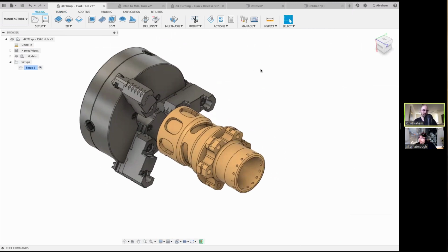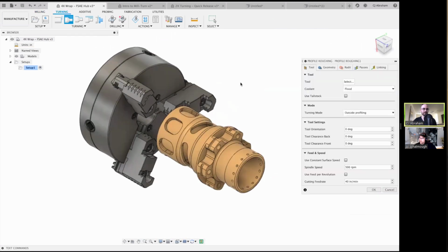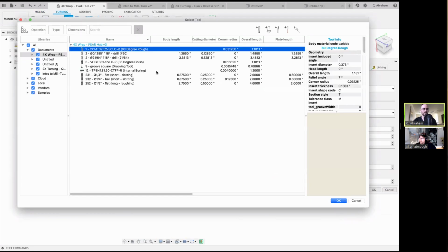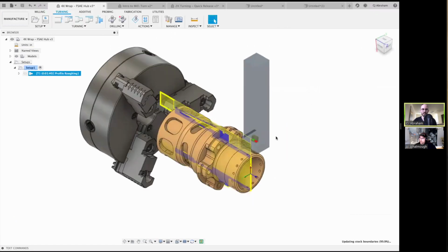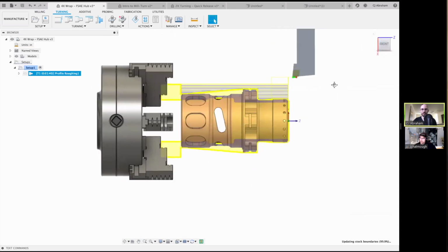Awesome. So, milling toolpaths. If you're doing mill turn operations, there's nothing you have to do differently per se to use milling operations. As long as you use the compatible post, it'll automatically configure all the points and things like that to use live tools on your mill turn machine. To demonstrate that, first I'll add a turning roughing toolpath to rough out this part. Just use the default settings. Okay, so we get a toolpath that will rough out this part.